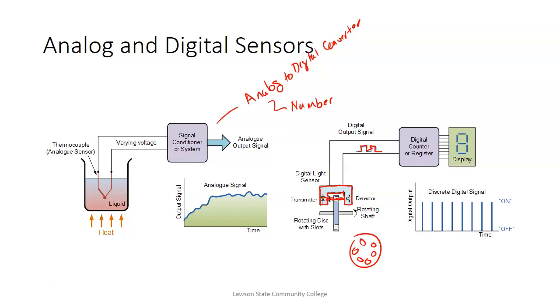We'd do a little math. So the programmable controller can't give you RPM directly, but it's a computer, so it has the ability to do math. So we could count the number of pulses over a second and then multiply it, and we could very easily come up with RPM on there. So that's the kind of tricks that you'll learn on a PLC. So this would be digital.